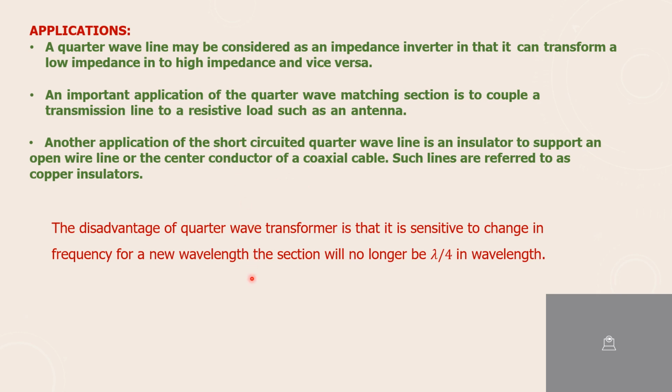The main disadvantage of this quarter wave line is that it is very sensitive to change in frequency. For a new wavelength, the section will no longer be lambda by 4 in wavelength. This is the main drawback in the case of the quarter wave line.